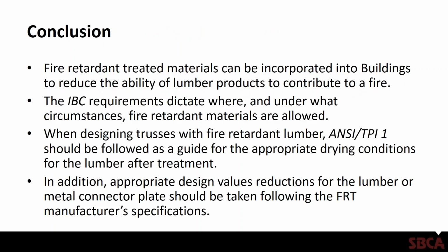So finally, in concluding, fire-retardant-treated materials can be incorporated into buildings to reduce the ability of lumber products to contribute to a fire. The IBC requirements dictate where and under what circumstances fire-retardant materials are allowed. When designing trusses with fire-retardant lumber, ANSI TPI 1 should be followed as a guide for the appropriate drying conditions for the lumber after treatment, and in addition, appropriate design value reductions for the lumber or connector plates should be taken following the FRT manufacturer's specifications.